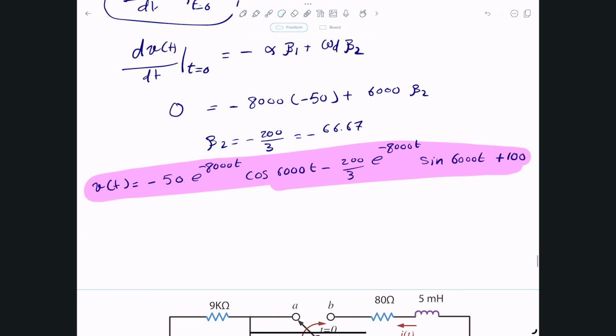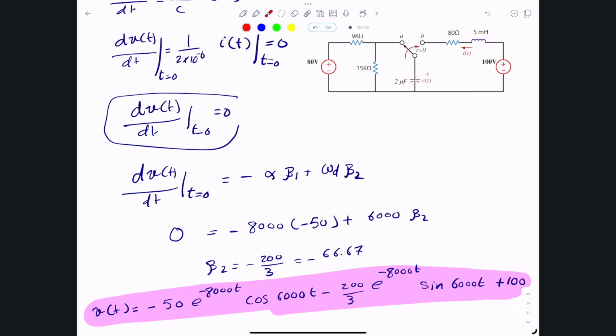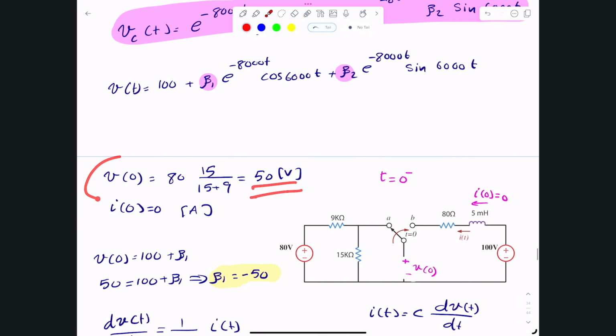So if we put the circuit one more time in here, when we take a look at it, what do we have? Well, if we put t equals 0, that will be 1, this will be 1, so I'll get negative 50. And when t equals 0, the whole thing here becomes 0 because sine of 0 is 0, so that tells me it's 100 minus 50. So initially I had 50 volts across this, and that's exactly what we got from the initial conditions in here. We got 50 volts for V0.